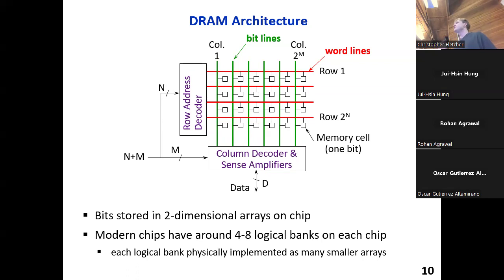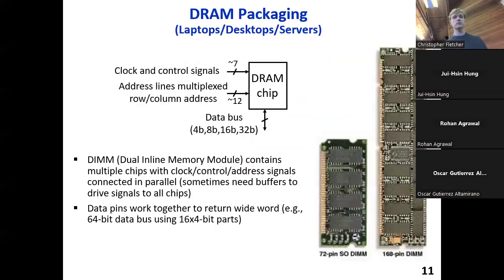This is a common degree of inflexibility that both DRAM and SRAM have. When you activate a word line, you're going to get all the bits out for that word, which may be more bits than you actually want, or for that matter, you actually own, if you look at it from a security perspective. And if you're writing, you don't have a way of selectively writing back. You have to read and then write. So yeah, this is a good question.